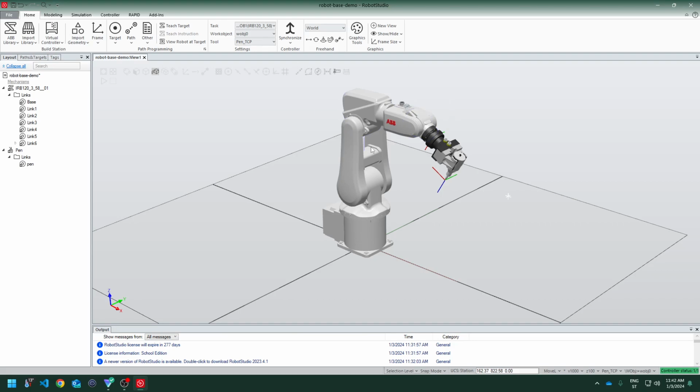Okay, now moving the robot. There are multiple different ways you can move the robot. You can specify the positions of joints. You can program it using Rapid, which I'm going to briefly show later on. But the simplest that you need for this task is just manually adjusting the position of the robot, because, at least currently, the task you have is, for example, writing some letters with this pen.